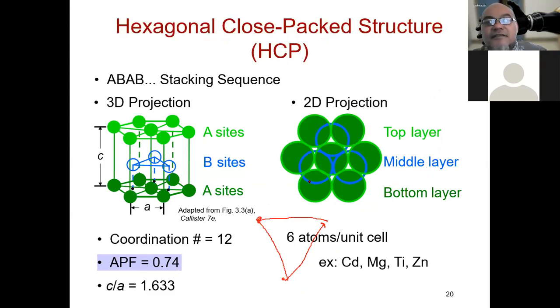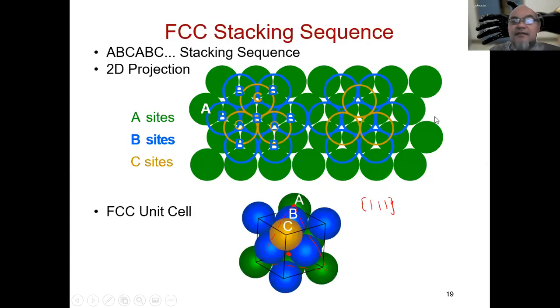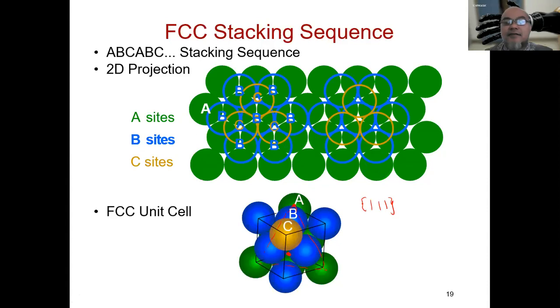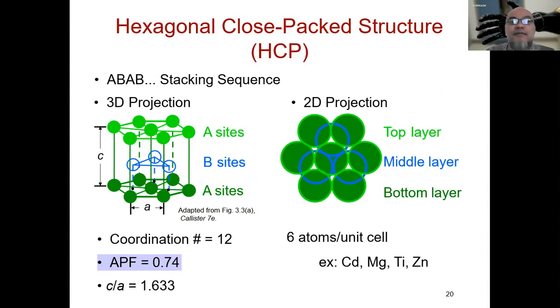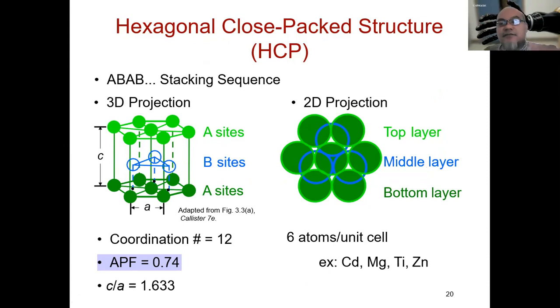Okay. So now, this is hexagonal. This is FCC, right? The previous picture is the FCC stacking sequence, where we stack the hexagonal 2D layer into the ABC stacking sequence. ABC, ABC, ABC. Another way of stacking is when we stack using the sequence AB, AB, AB.